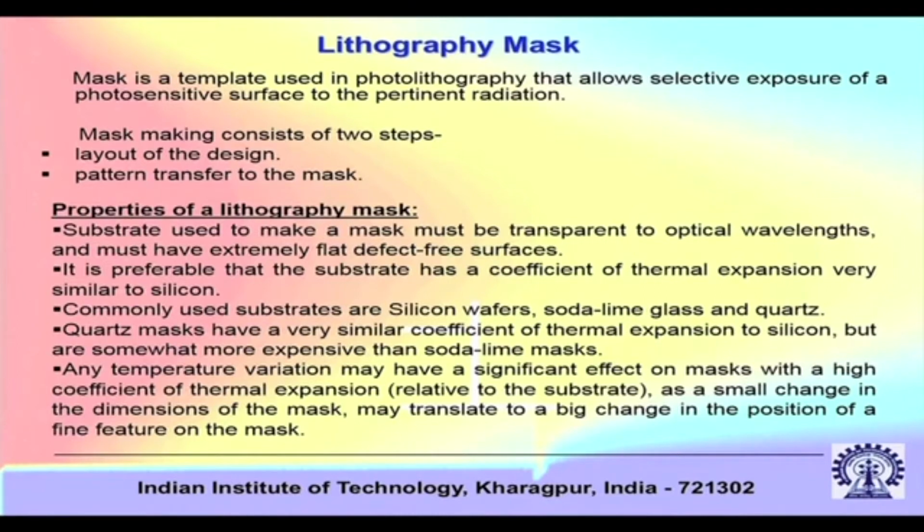What are the properties of the mask? The mask must be transparent to optical wavelengths and must have extremely flat, defect free surfaces. It is preferable that it has a coefficient of thermal expansion very similar to silicon. Think of the mold and the pattern in casting.